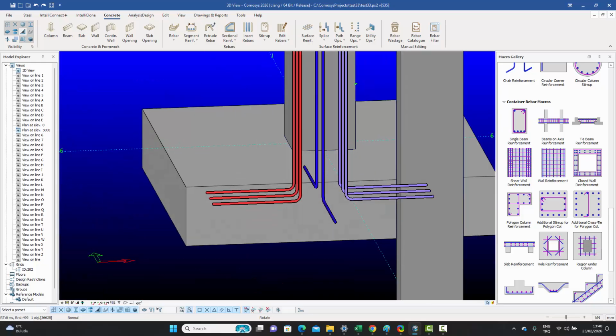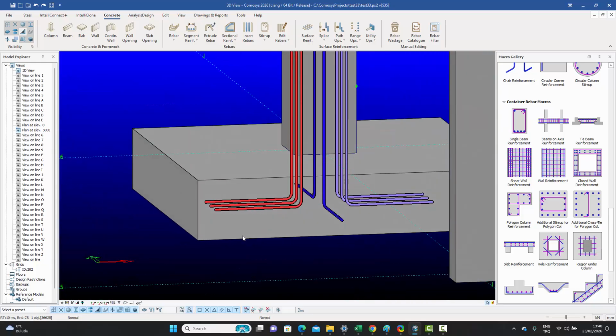But normally this foundation will have its own bars as well, the main reinforcement and the secondary reinforcement, and these bars will need to sit on top of those. So if we were to calculate exactly, let's say we want to use 20 millimeter rebar over here, and 20 in the secondary direction, so that's another 40. 50 was the clear cover, so 50, then 20, 20 for the two bars, that's 90, and then the middle of that would be another 8, so that's 98.